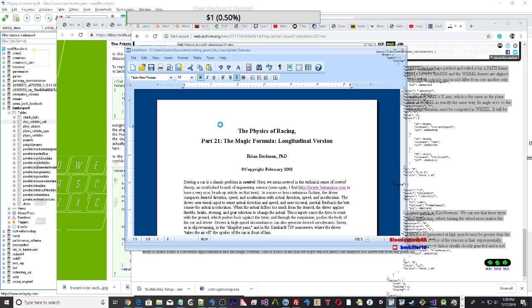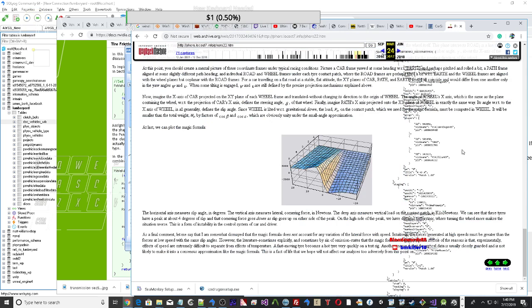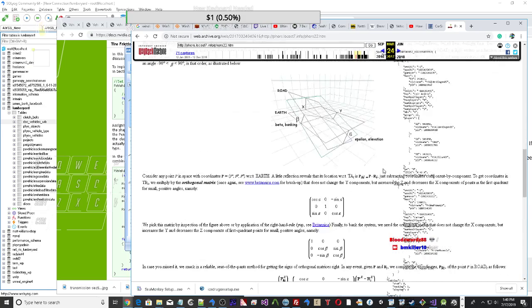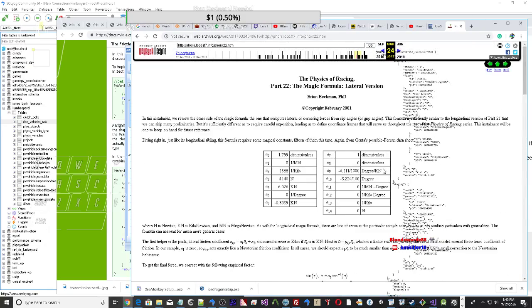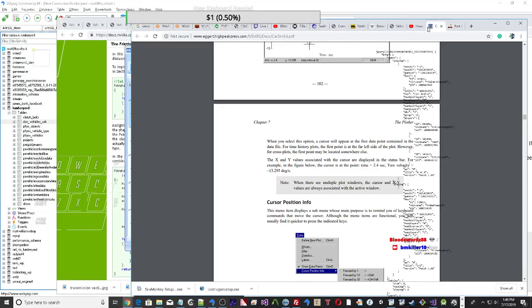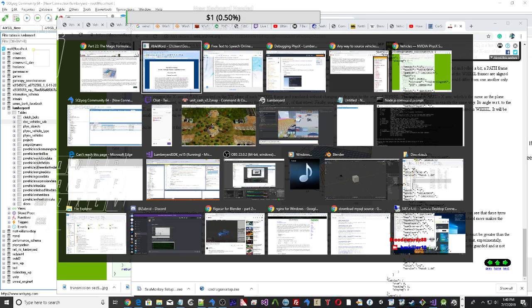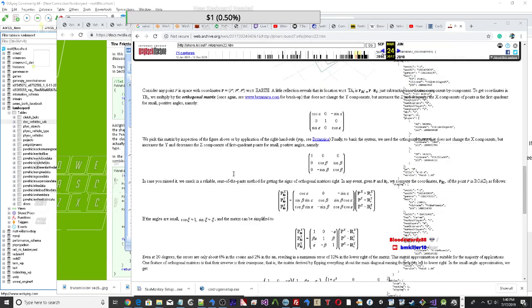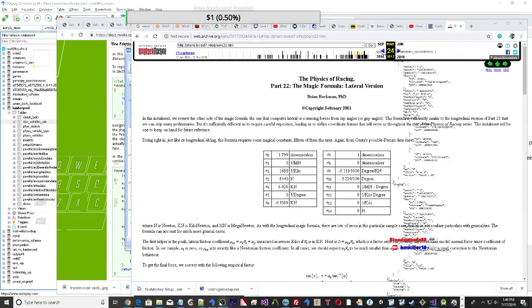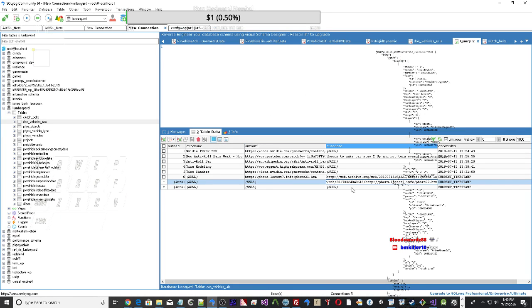As a consequence, the functions setWheelCentreOffset, setSuspForceAppPointOffset and setTireForceAppPointOffset all describe offsets from the rigid body center of mass. The indirectness of this approach can make changes to the rigid body center of mass a bit more involved than might be expected. To solve this problem, the function PxVehicleUpdateCMassLocalPose has been introduced, though not used in the code above. This function recomputes and sets all suspension offsets, recomputes the sprung masses and sets them in a way that preserves the natural frequency and damping ratio of each spring.